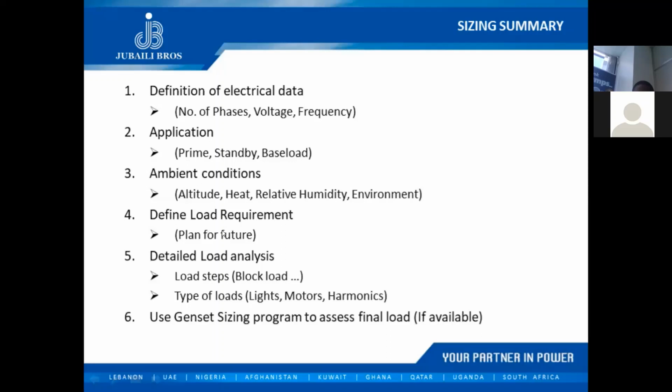Now, considering all of these, if you have, let's say, a given load schedule with hundreds of loads, typically you'd start off by selecting an engine and alternator that would cover all this running load. In case you have harmonic loads, which we briefly discussed, you'll go to a sizing software.